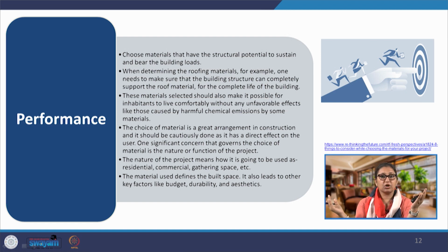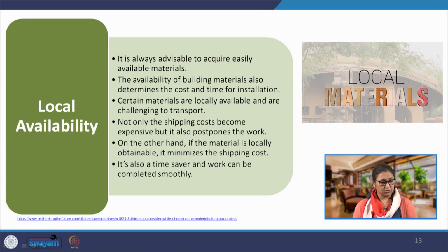The UV is not required at all, it has to be cut off. So, this is my performance criteria and so the specification would be a spectrally selective glazing. So, when we say performance, we are looking at specific performance criteria and then we will frame the specifications accordingly and define the rest of the factors. Now, which factor takes precedence depends upon the context, the building that is in question.